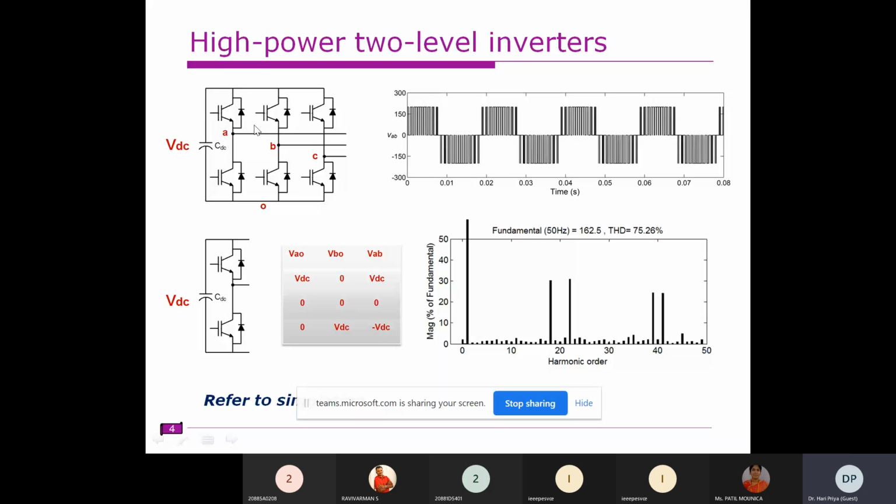So what is the advantage of self-commutating devices? They can turn on and turn off by themselves. That means depending upon the gate pulse, it can turn on. If you remove the gate pulse, it is going to turn off. It's all about the triggering pulse control. So these are very much advantages in terms of flexible control. So what they have done is taken the basic inverter and replaced each line commutating device with a self-commutating device. It is the first generation, or else you can say the improvement in the first generation inverters. So if you see the second one, I said it is two level.